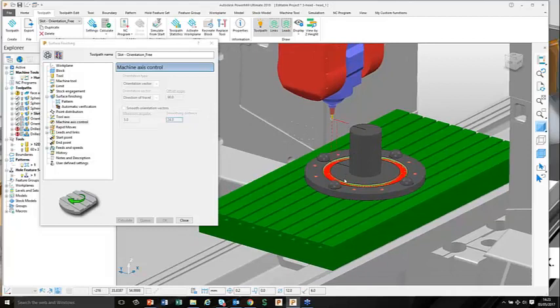So that's the difference between fixed and direction of travel. Again, very similar to polar. If you've got an awkward pocket here that you need to area clear, there's nothing stopping you doing fixed direction. Or if you've got a circular pocket here, there's nothing stopping you doing direction of travel and doing an area clearance while it's following the direction of travel. Just be wary of the connecting moves between toolpaths, and again, think about using start point rather than block center safe.